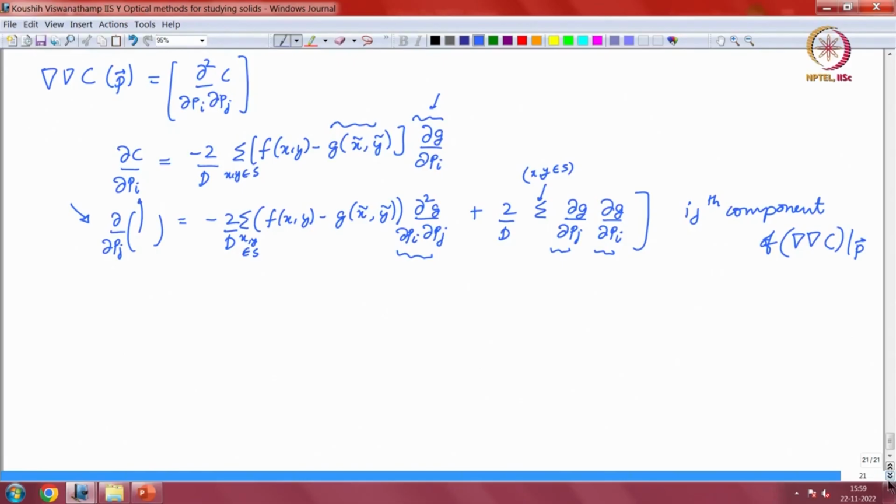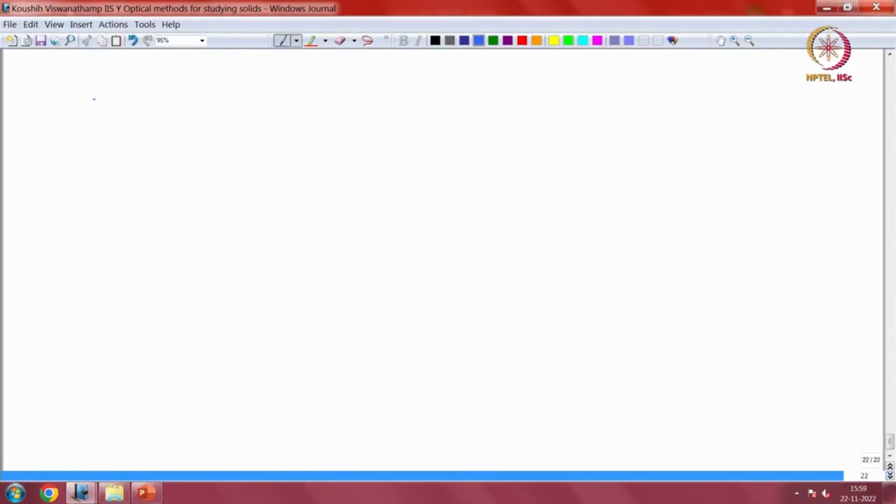Once you have the strain fields, you will have this discontinuity between cell I and cell I plus 1 for instance, comma j, or window or subset located at I comma j and located at I plus 1 comma j for instance, and you have to do some interpolation to ensure continuity.